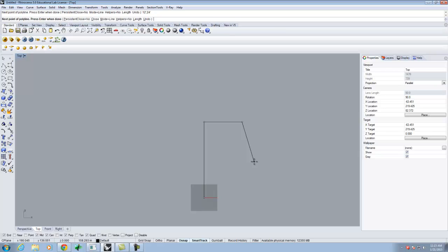and we had a point, we had a line that went here, we had a line that went over to here, right? Remember this was 12 feet, 24 feet, right? If we switch and we use relative coordinates, it's going to say now this point right here is now 0, 0. Where do I go? Right? And so in this instance, we're going to go down 6 feet to this point.